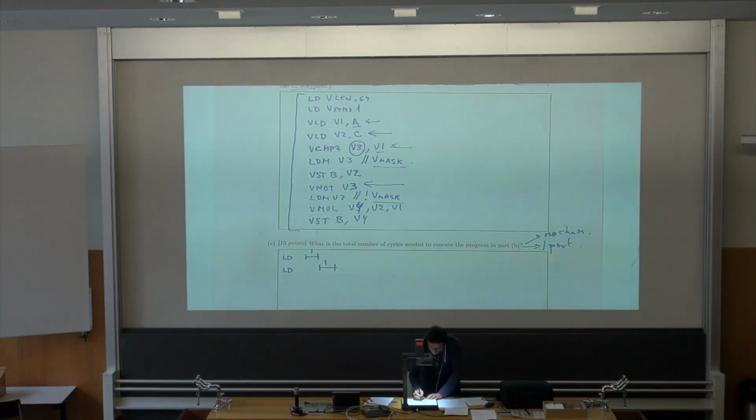Then we have the next instruction, again a load for the vector stride, so it's again one cycle, and then we have the vector load that will start right after that. The vector load for the first element will take 22 cycles, and right after that we will obtain one output every cycle. So this is going to be 64 minus 1, that is 63 cycles, right? And then we will issue the next vector load.